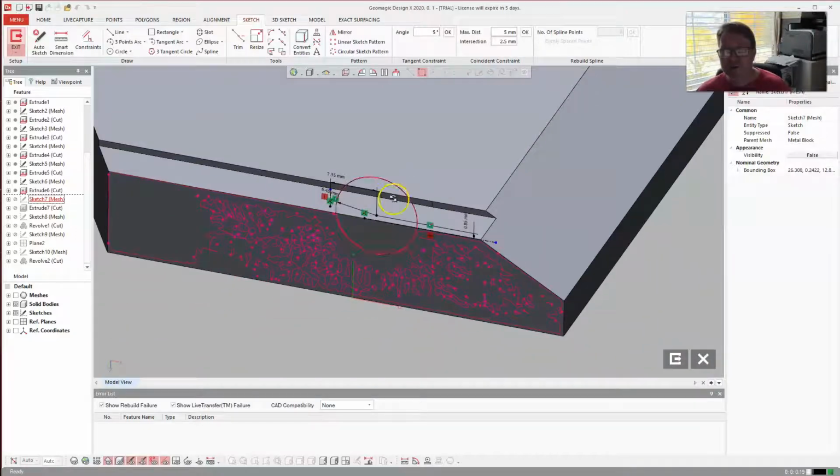This goes to show, though, if I'm looking at how the mesh morphs, this plane that we're drawing off of is not exactly perpendicular. So I guess you can say in Geomagic Design X, the scan data and that plane don't perfectly match a flat surface. It's just ever so slightly tweaked. So every time playing with this number, I can't find a perfect spot to put that circle to get it to cut straight through, because the plane is not perfectly flat. So getting close enough is just playing with it.